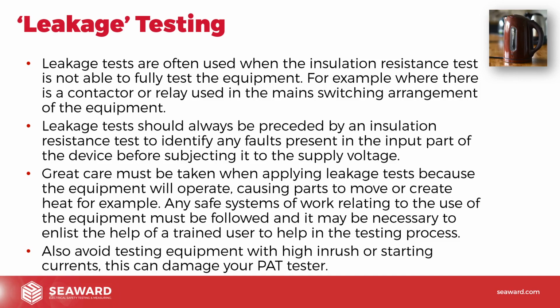And especially, like anything, if you just keep doing that over and over and over again, you're going to damage your PAT tester and you're going to have to send it in for repair and you're going to get a bill. So always think about equipment starting currents and inrush currents. And if you're not sure, speak to the manufacturers, or there are potentially strategies where you could measure the current and things like that if you needed to. But always think about it when you are doing these tests, because quite often people don't understand that they can actually damage equipment by doing these tests. So always think about that when you are performing a leakage test.